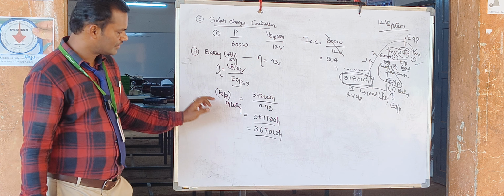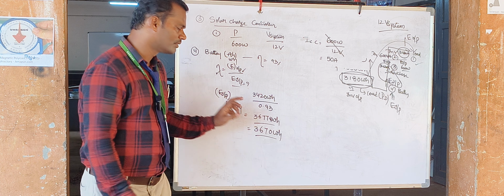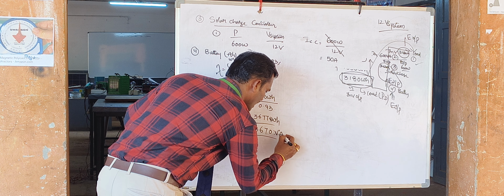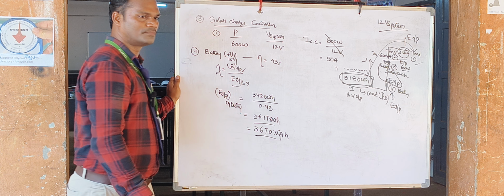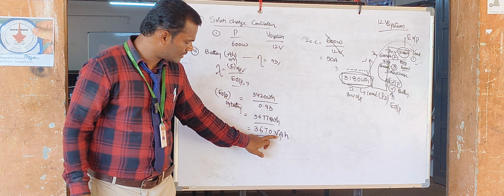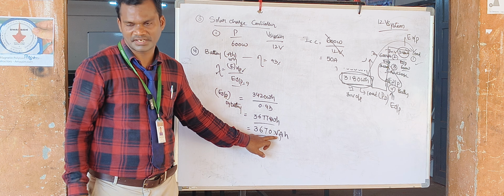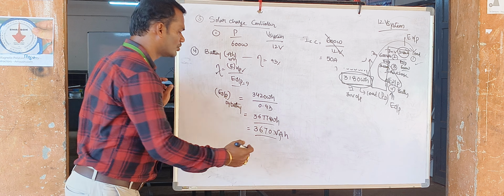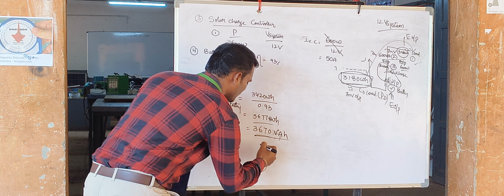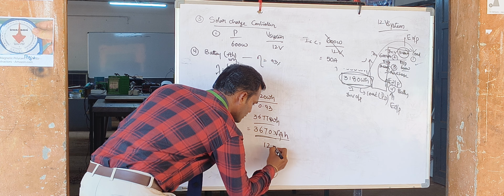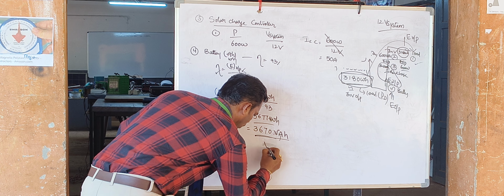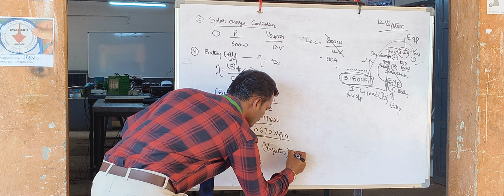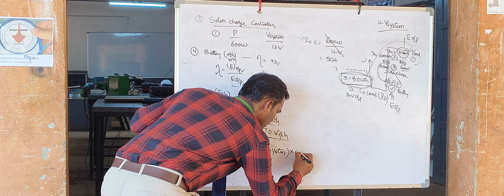Now what to do is, here you can see the rating. It is a product of, how to write down watt hour? Voltage, ampere, hour. But what is creating a problem for me? Voltage is creating a problem. That's why we want to divide this energy by volts. So I'm writing the input energy divided by system voltage into depth of discharge.